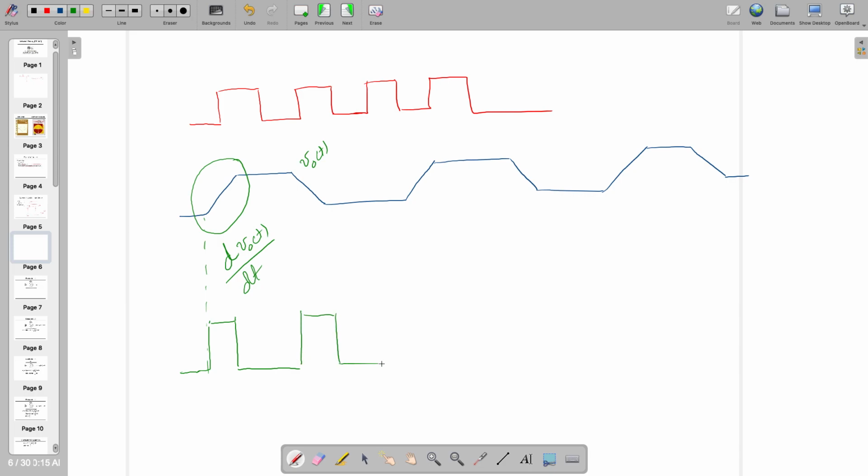So this impulse function was invented, and it is very useful for this case, that the derivative of step response is actually impulse. If you forgot, then I'll tell you, d by dt of step is equal to impulse, or the train of impulses, right? So that is what we are going to use to find out the things in our circuit.